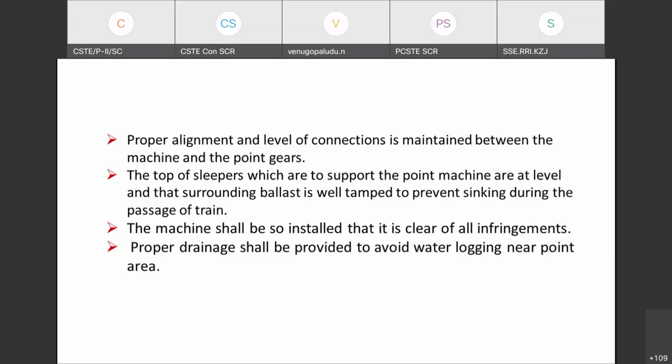This problem you are facing while replacing the ground connections, not the point machine? Yes, sir, while replacing ground connections. While installation, if we provide the close switch with a close notch, it is okay, sir. But when we replace corroded ground connections with other ground connections, the general tendency of a universal point machine is 1, 2, 1 and 3 and 2 and 4 are the pair, sir.